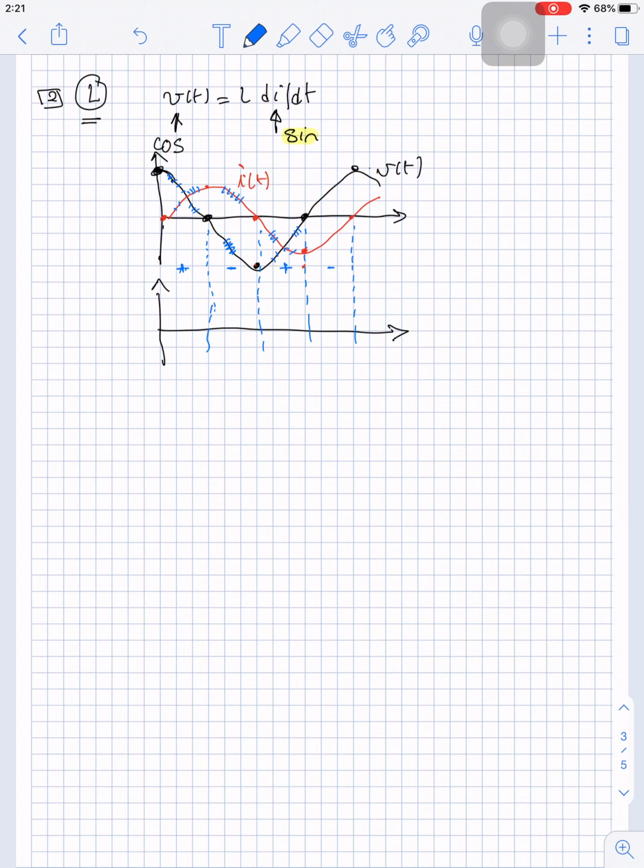So the inductor is taking energy, converting this energy into magnetic field, and storing this magnetic field into what is called a core, a magnetic core. Then it can release this energy again from the magnetic core. So the inductance is acting like an energy tank. You can store energy into inductance in the form of magnetic energy or magnetic field. So the inductance will take the energy, store it as magnetic, then it will supply it again.